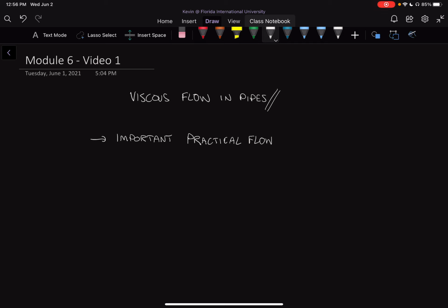So we have to estimate this solution to come up with a good engineering solution for the problem. This comes from looking at all three methodologies: a control volume approach, a Bernoulli approach, and a more differential approach, and also looking at experimental data to understand our flow.